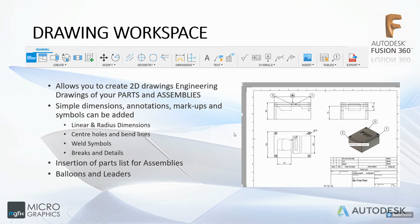Okay, let's move on. Now we're taking us to the drawing workspace. In the drawing workspace, we'll be able to document our design and see what we have. It allows you to create 2D drawings and 2D engineering style drawings. That means annotations and part notes and markups and that sort of thing. You'll be able to do simple dimensions, annotations, markups, and symbols. I've listed a few here: linear and radius, holes, bend lines, weld symbols, breaks and details, and zoom into certain areas.